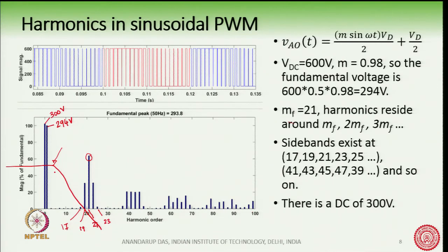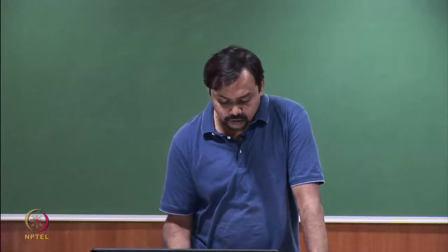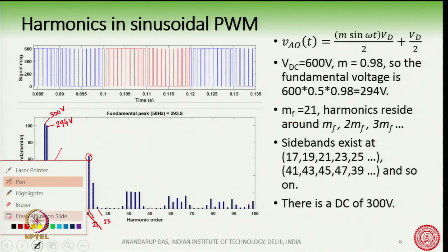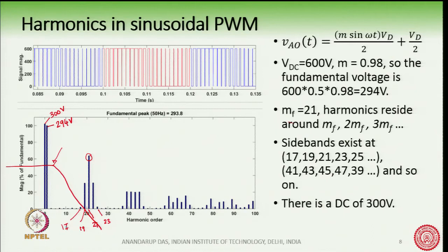So, if we choose a higher and higher MF value, then the filter frequency can be pushed further to the right-hand side. For example, we can push the filter if the MF is higher, relative to the first band of harmonics. Let us take an example.